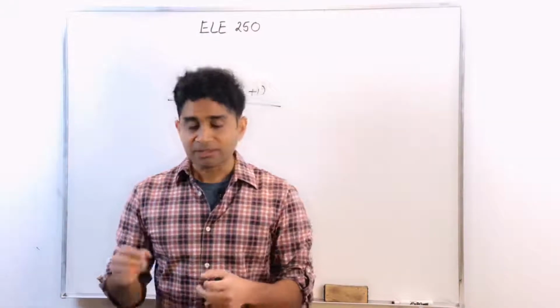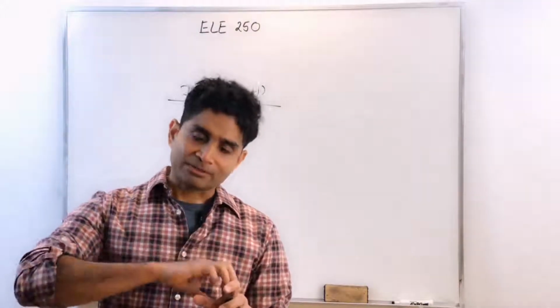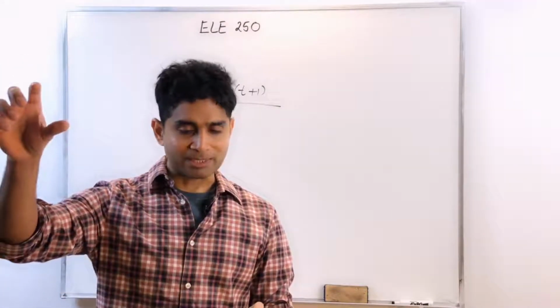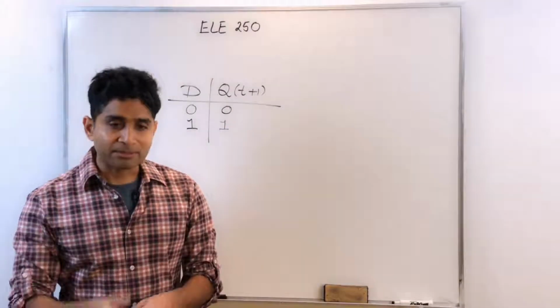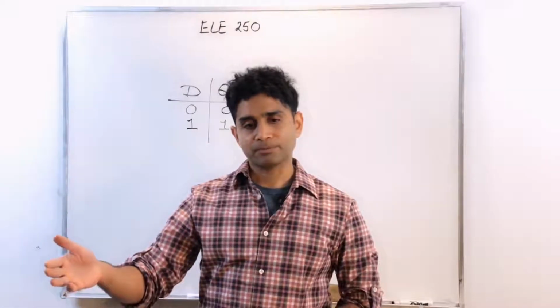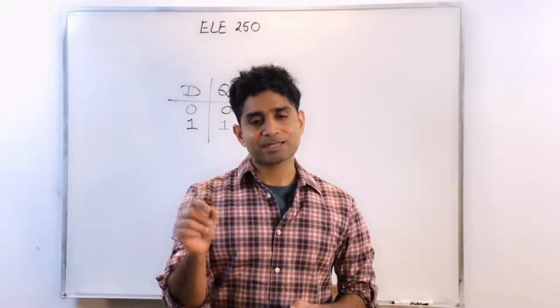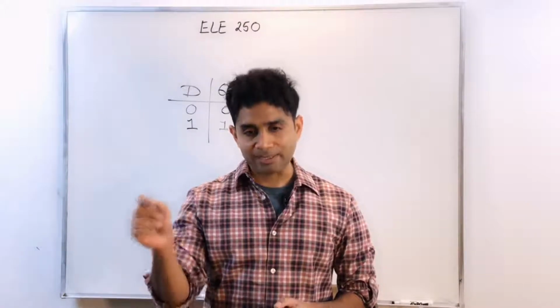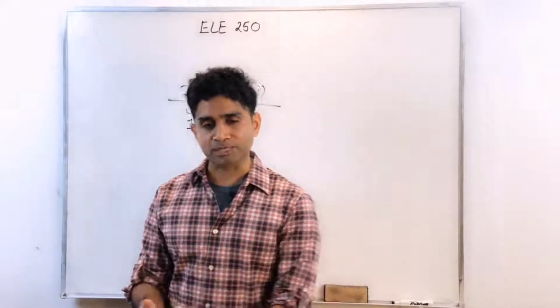The reason we need this is that you have this common data bus, the bunch of data lines, connected to multiple registers, and I should be able to pick and choose the register I want to store that information in at a given instant of time. This load enable allows me to do that.